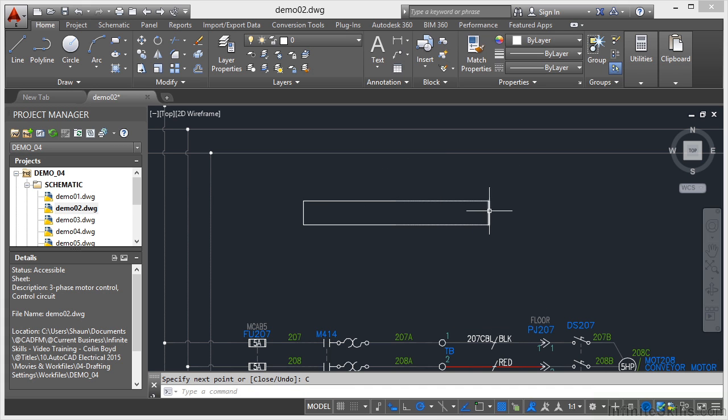Okay, it's made up of separate line segments, sure. But each of those is drawn exactly at the appropriate degrees and the appropriate distance. That's what polar tracking is all about. Now, the distances that I've input there are known as direct distance entry. So as long as you've got an angle, you can then place a line at that angle using a direct distance. Now, what I've done there is use the default 90 degrees.